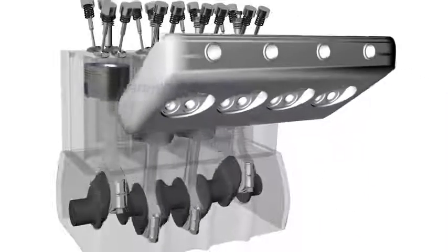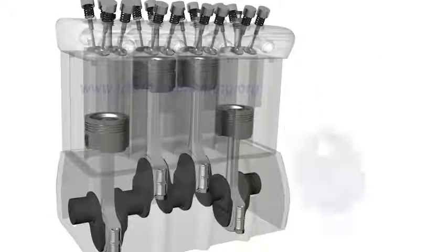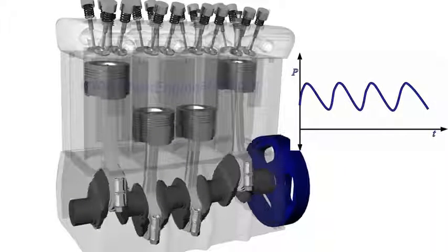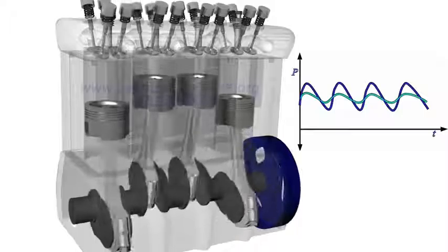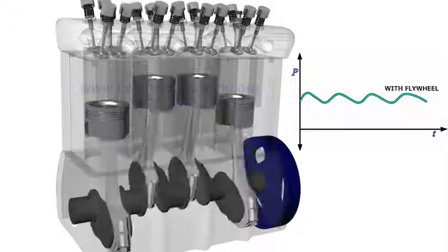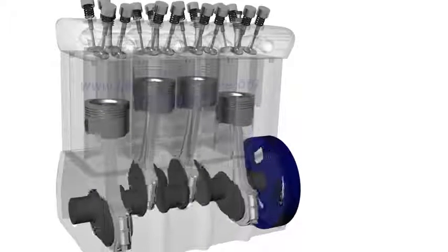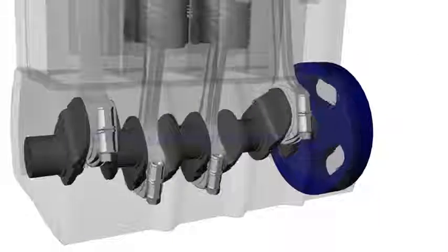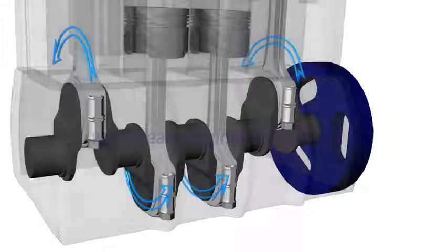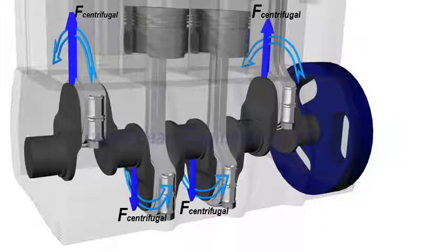A heavy flywheel which acts like a power reservoir further helps in smoothing out non-uniformity of power. A huge unbalanced force arises in the form of dynamic unbalance due to the excessive mass at the connecting rod side. This is negated by providing counterweights on the crank side.